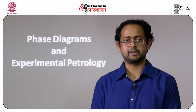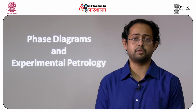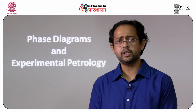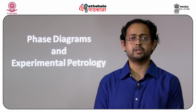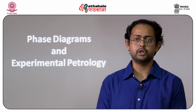required. Say for example in forsterite and silica, if you look at the formula, forsterite is Mg2SiO4 and silica is SiO2. So out here you do not take the components as magnesium, silicon and oxygen, you just simply use MgO and SiO2. So out here the components would be 2.